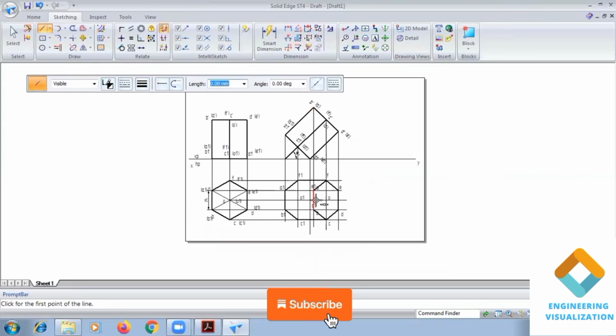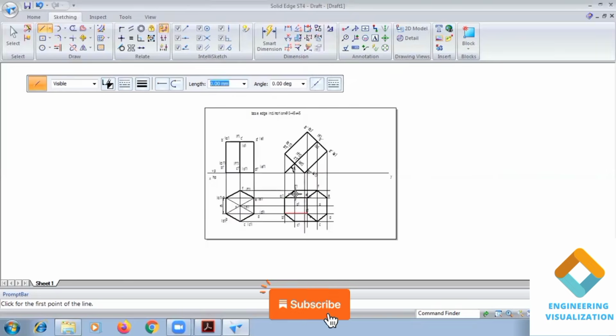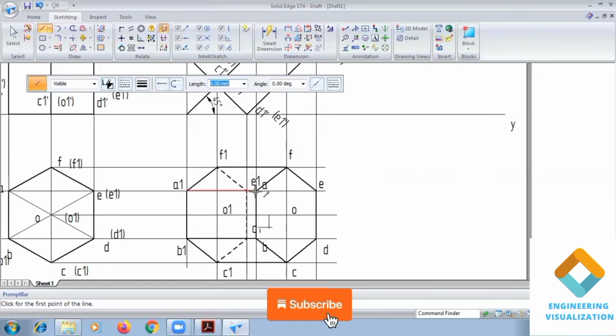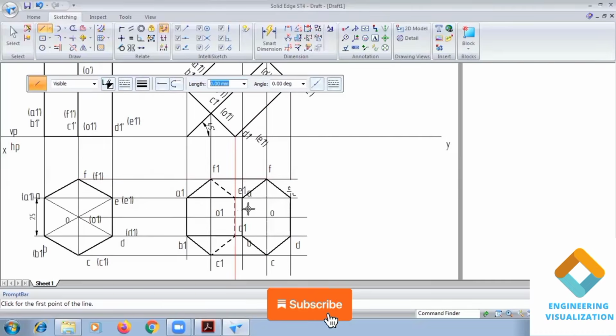And this rectangular face is also visible. This hexagonal base is not visible from the top view. So it is drawn with the hidden line. Okay. Here this slanted rectangular face is also not visible. You can show part of the line here from here to here.